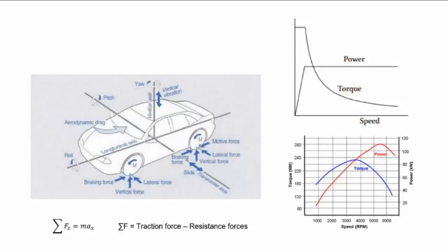Okay, traction force is tractive effort actually. It means that tractive effort is the force applied on the wheels at the road surface in order to move the vehicle. The available traction force is limited by two factors. Traction force generated by the drive system. What are the components of the generation? Electric motor and maybe we can say gear. Okay, electric motor and gear. This means the drive system. Also, next one, weight distribution of the vehicle on the road.